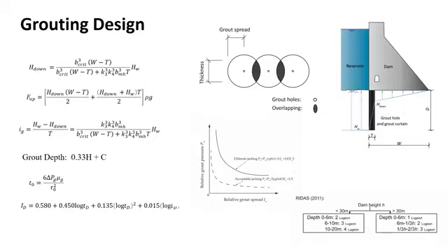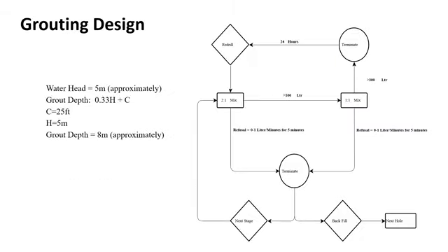This slide presents the key equations and relationships used in the design phase of the curtain grouting process. It includes the formulas applied to determine the thickness of the grout curtain, and the depth of individual grouting intervals. Additionally, it illustrates the equations and graphs used to estimate the appropriate grouting pressure, ensuring the prevention of hydraulic jacking and the reduction of uplift pressure on the dam foundation. Using these numerical methods, a curtain grouting pattern was designed for the rainwater harvesting project in Vadamarachchi lagoon.